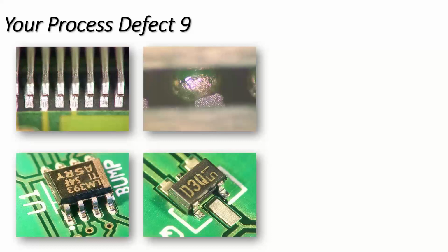But modifying placement data to make sure the parts are where you want them on the pads, I think is fundamental. The problem does come if you continually make changes, then the data is a very bad representation of the original data you've got. And I know some companies don't like to change data for this very reason. But I don't want to use data which isn't allowing me to give the customer what he really wants, a good product. So again, communicate that, discuss that.